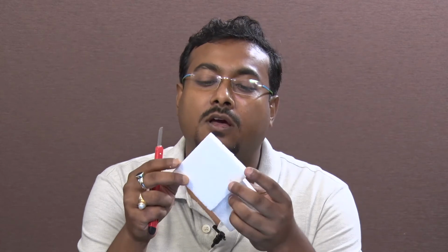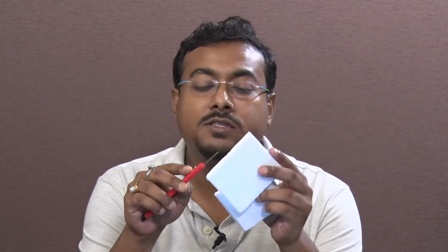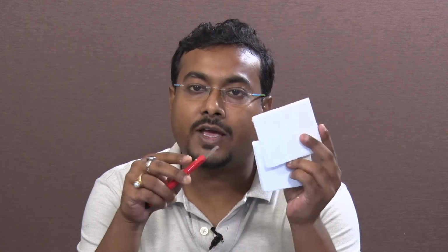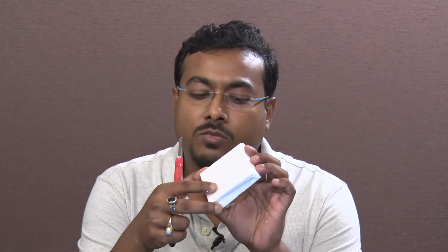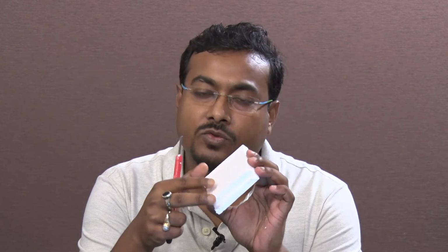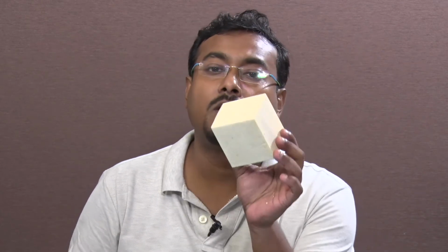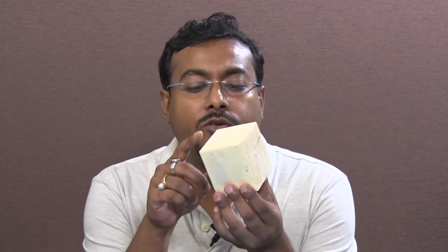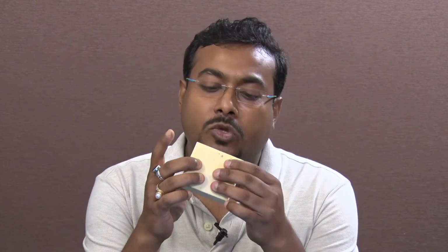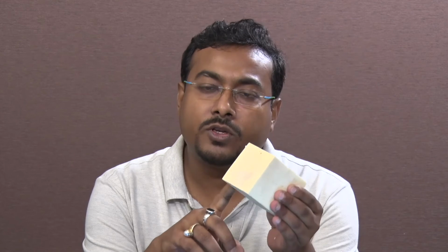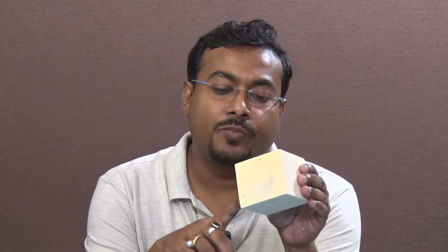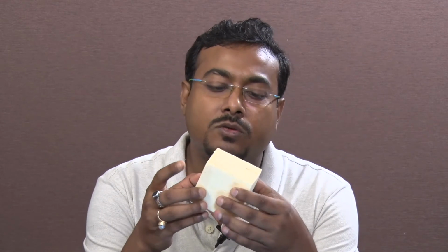Low density thermocol you can just cut as straight lines or curved lines, but you cannot give organic form to this low density thermocol, because it is very soft. While sanding, the granules come out. Next is polyurethane. Polyurethane is very useful material. You can use polyurethane with CNC milling. Within a closed chamber you can use polyurethane.